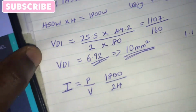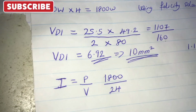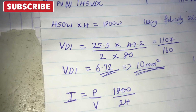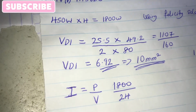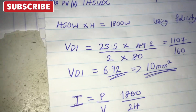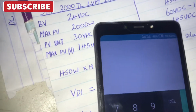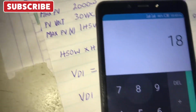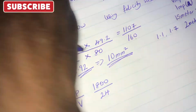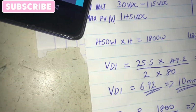So power 1800, that's the maximum power that the panel can produce, divided by the battery voltage where the power is going to, which is 24 volts. So let's do that. 1800 divided by 24, giving us 75. So our current here is 75 amps.